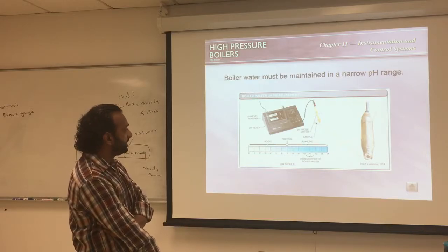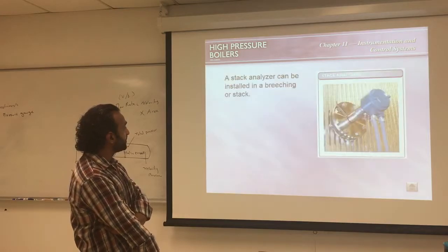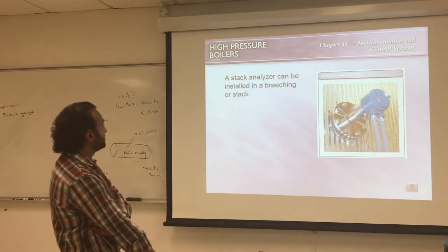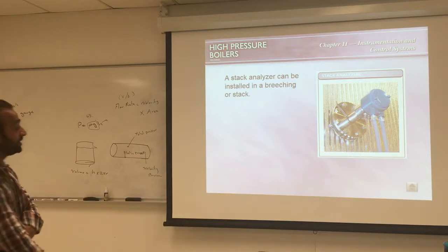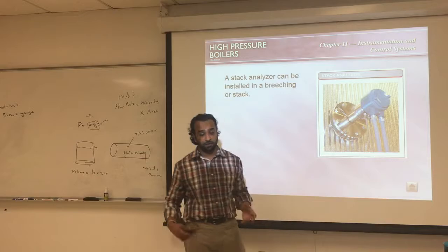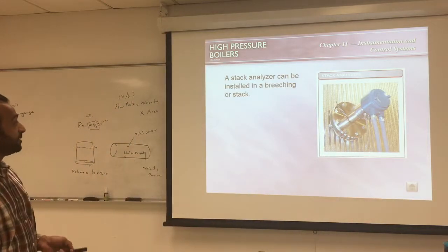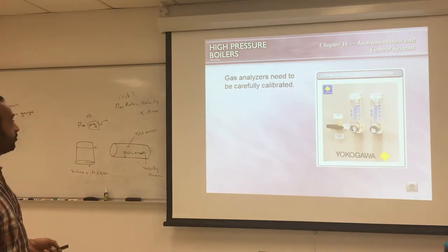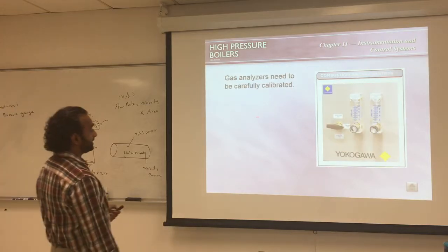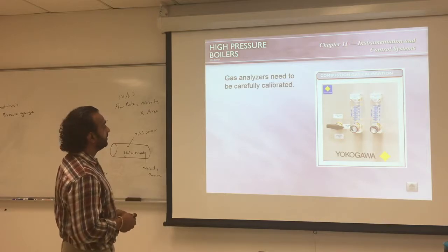pH measurement, again, that's something that can be done either live or through a test. Stack analyzer, this is also interesting because it measures the thickness of the soot inside the plate. So if it gets too thick, then it's time for you to turn on the brushes or the steamer. Gas analyzer, they also analyze the gas and how much is coming out of the stack.